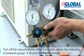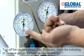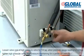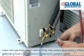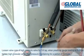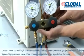Turn off the vacuum pump. After 5 minutes, check the indicating of pressure gauge. It should have no change. Unscrew valve cap of high pressure valve and low pressure valve, and loosen valve core of high pressure valve through turning it for 1/4 lap counterclockwise with hexagonal socket for 5 seconds. Generally, turn off valve core if pressure gauge reading is about 0.5 MPa.